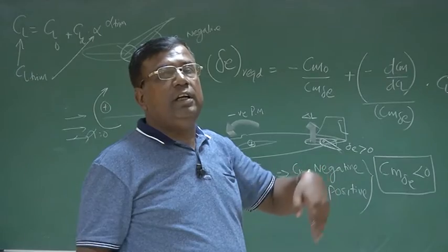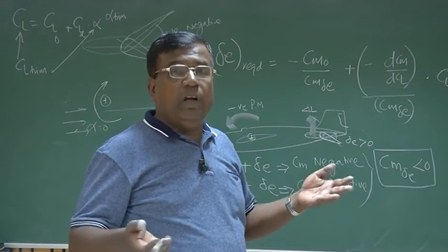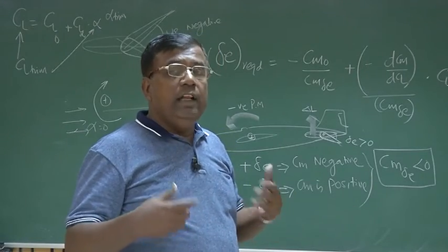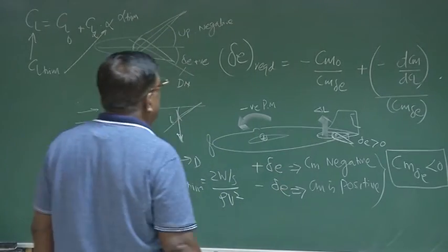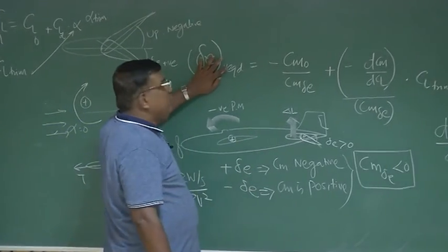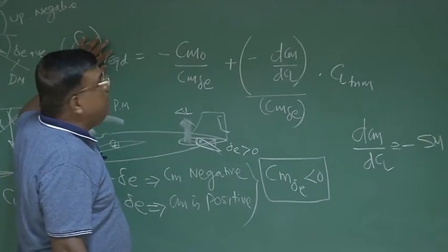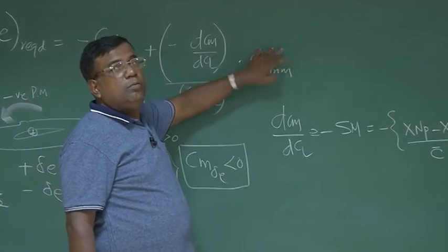So it will not generate lift at all, or very small lift, with more drag, because the flow gets separated. That is the point where you say the elevator is not effective. So we need to constrain this. You say, oh dear friend, I have a limitation, so I can only control it to my best strength. So it cannot be any CL trim, it has to be a limited CL trim.